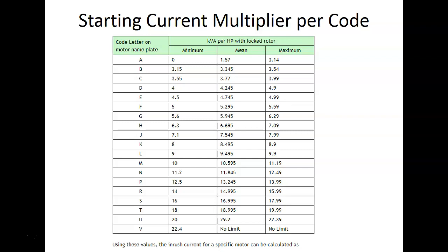Maximum starting current would be, then you'd probably multiply that by what? 1.25. And then if it's not a standard value, you do what? Round up. So 6 to 8 is just a rule of thumb if you can't have access to this chart.